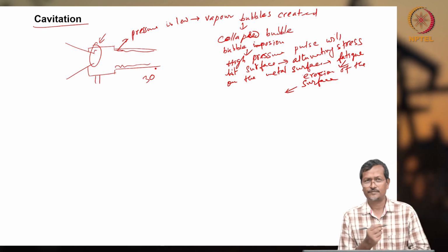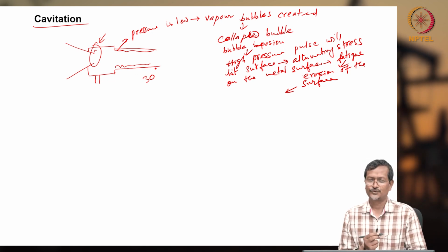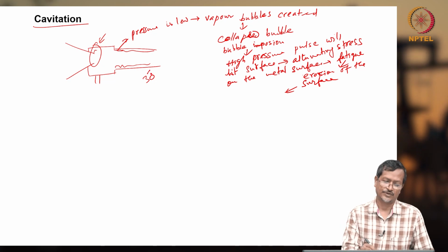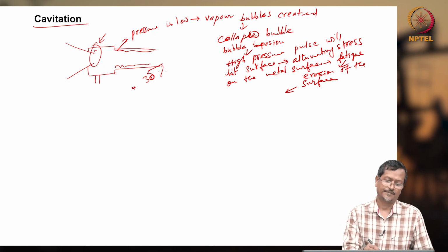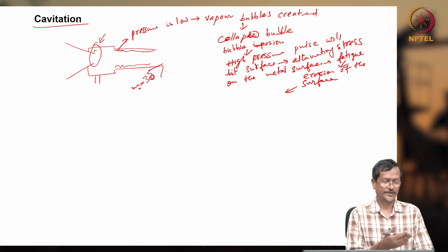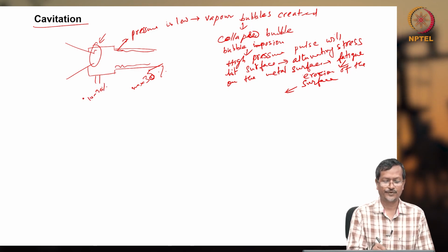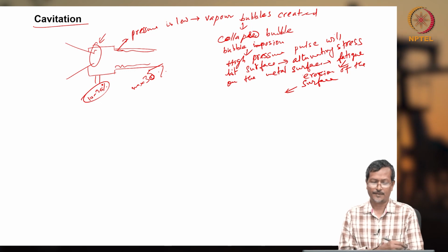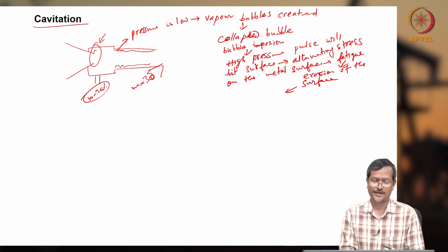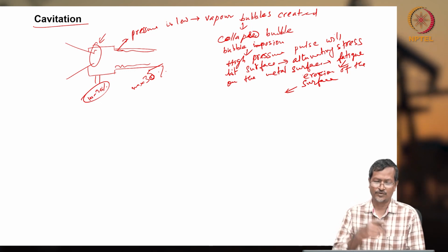Yeah, we are doing some research on jet pumps, and we got a maximum of 35% efficiency actually. Okay, maximum. Normally the books report 10 to 30% efficiency. Okay, so this is reliable. 10 to 30%. So even getting 30% will be difficult if you consider the whole system actually.